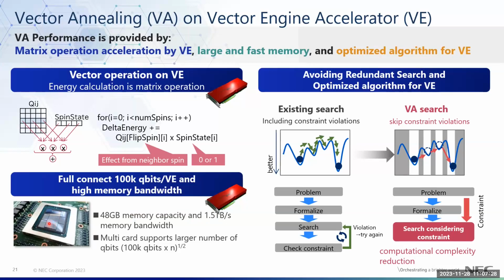So if you compare this with the AVX of Intel, AVX2, I think, has 512 bits worth of vector extensions. So 512 bits on the CPUs compared to 32K on this, and 64 of those. That provides a very good platform for these kinds of computations.